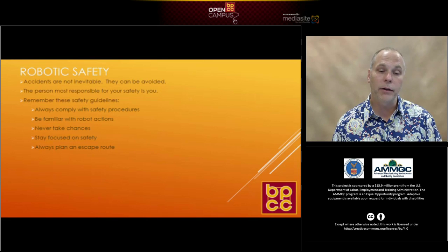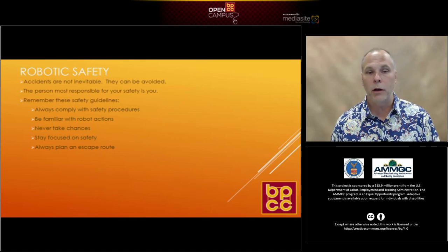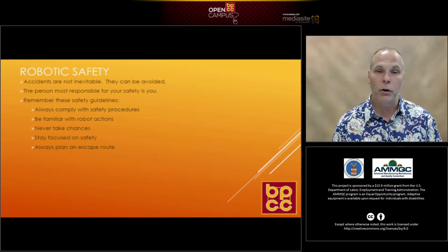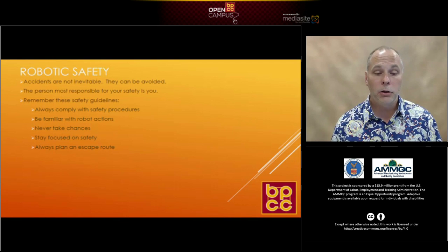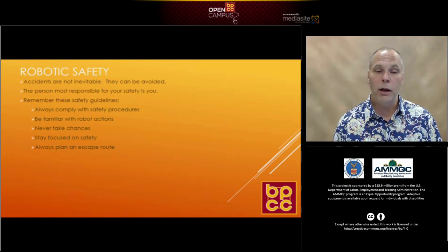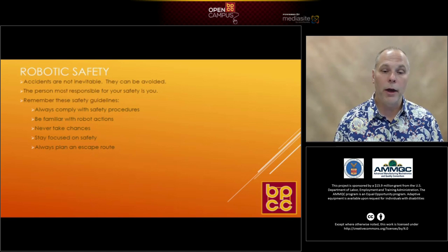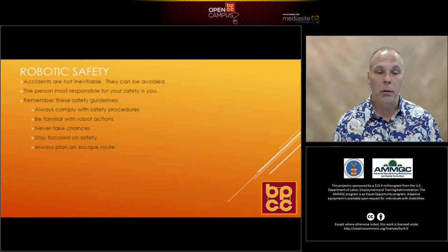Stay focused on safety. As we mentioned earlier, put aside what's going on in your mind or at home or in your personal life so you can stay focused while you're dealing with robots. And then also, always plan an escape route. If you're inside one of those work envelopes, I always know that I need a way out if something should happen. So know and plan accordingly.